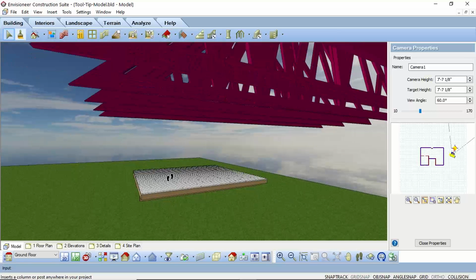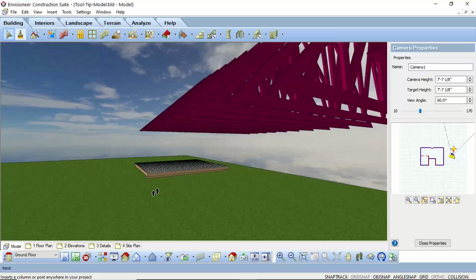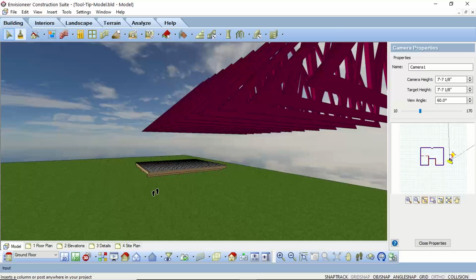So if you want to paint a deck or a truss profile, you need to assign those members to have that color, and then assign that member to be used in that particular deck or in that particular truss run. So that's how you could paint and get a different look for those two particular elements.